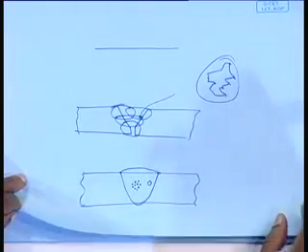Naturally, porosity has to be removed, that is a gross defect, and it is an internal defect at the same time, because it forms within the fusion zone. Porosity is a cluster of small bubbles, blowhole is one big bubble. For some reason, some gas bubble may get entrapped. Generally, blowhole is not observed in welding.